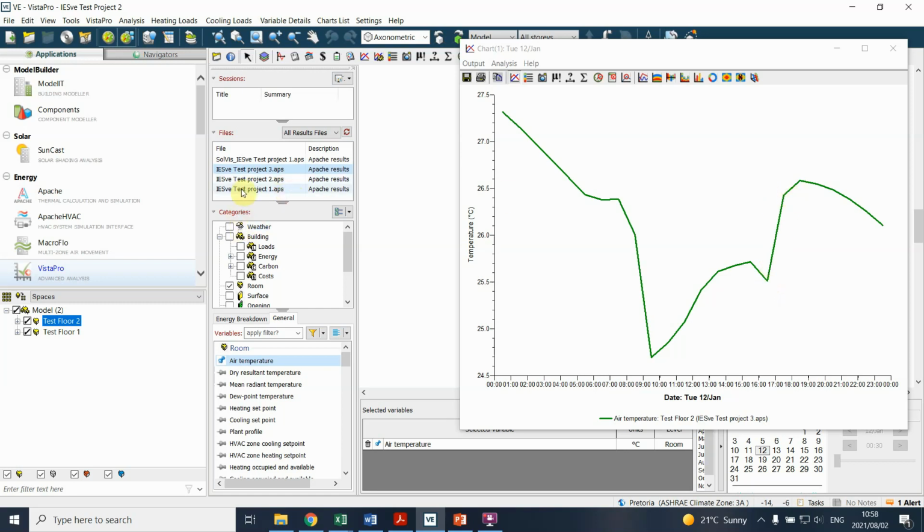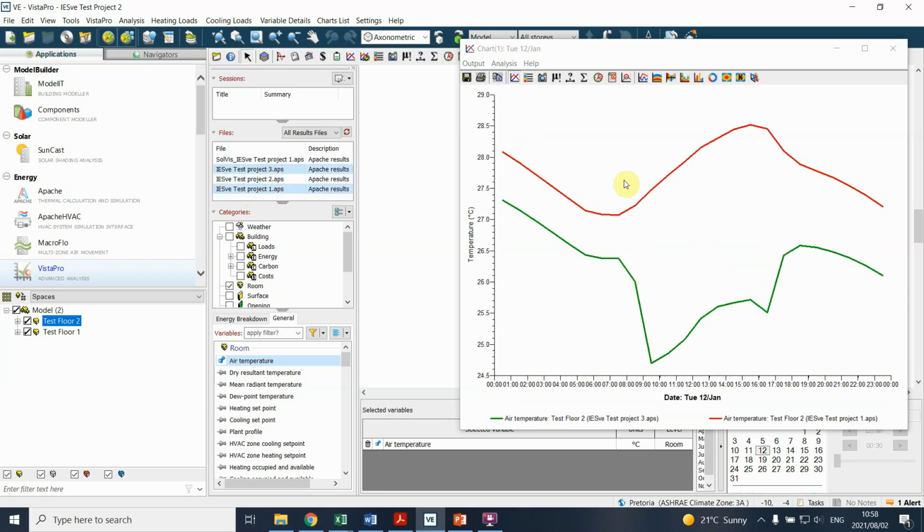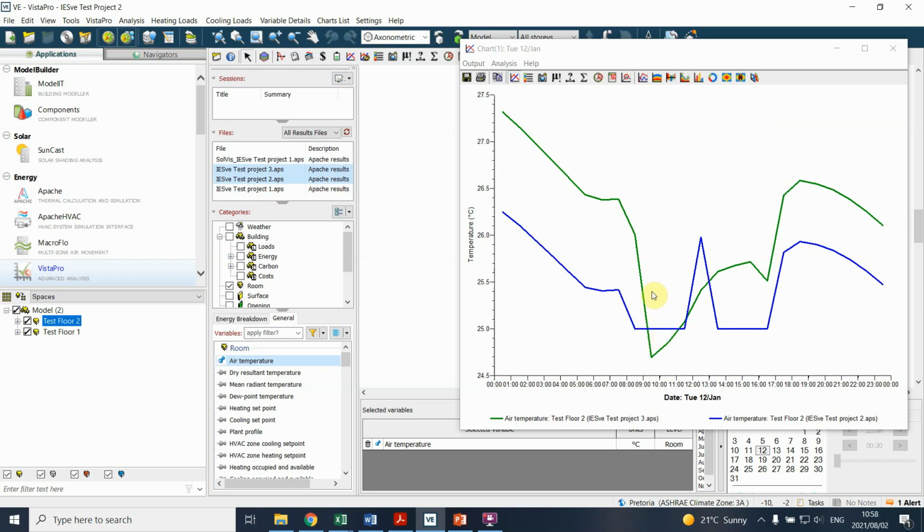Now you'll see it most clearly when we start comparing the two models. Now remember, these are the two naturally ventilated models. The first one simply has an S-curve that basically shows that as people enter the building, there's heat being gained inside the building. So clearly there's a difference when you start opening the windows, and that is within the model. But we can see that if you compare the two to air conditioning, then there is a slight drop below 25, and then we don't necessarily get there.